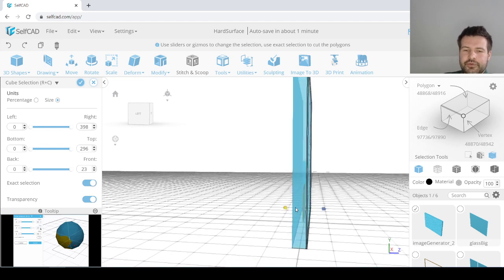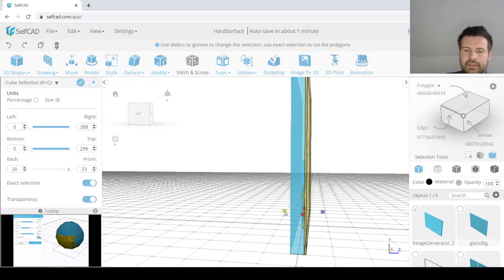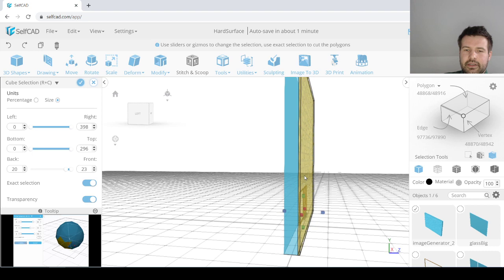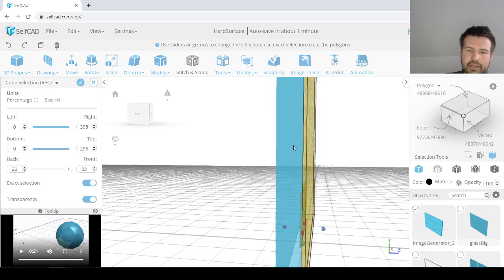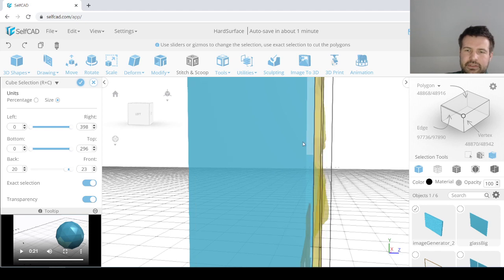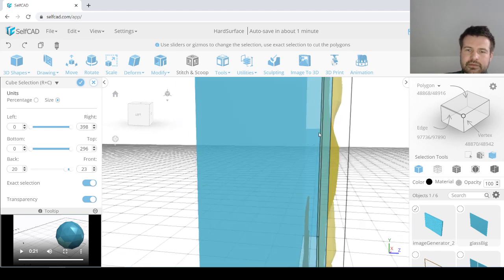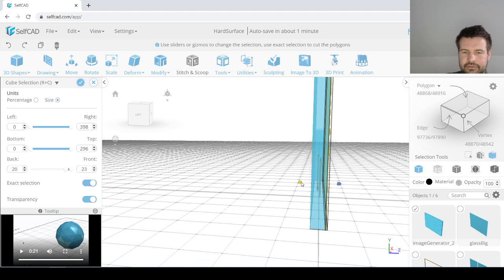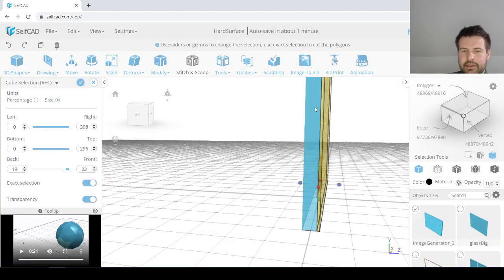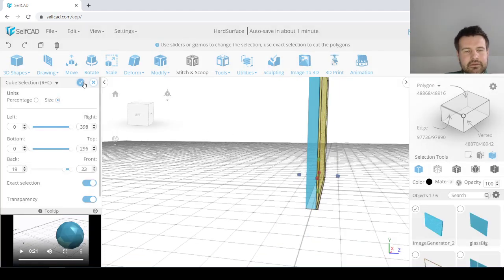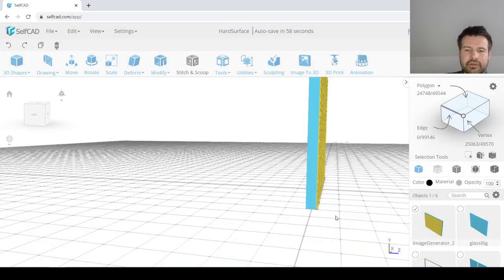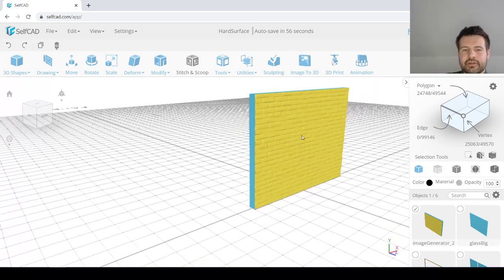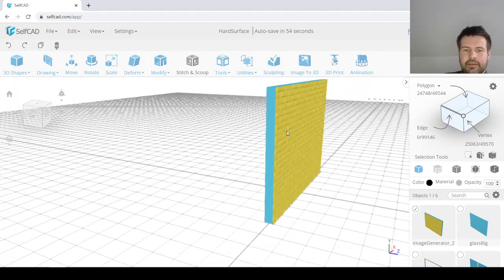The way I'm going to select is I'm just going to make a slight offset on the Z value here, just to select it this way. And I need to increase it a little because this might not really cover exactly. The reason for that is quite simple: if we connect this later on, there might be holes, which I will also explain in a minute.